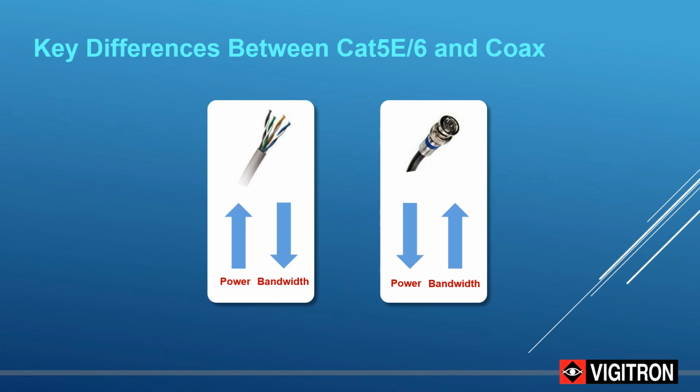So what happens there? Well, as we go higher in power, we use more wires within CAT cabling to handle it, but bandwidth is reduced. Coax cable, on the other end, because of its characteristics, is an excellent carrier of bandwidth, but again, we're only dealing with a single pair of wire, and therefore its ability to transmit PoE is significantly reduced to 37 watts maximum.